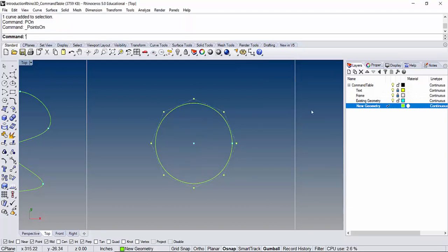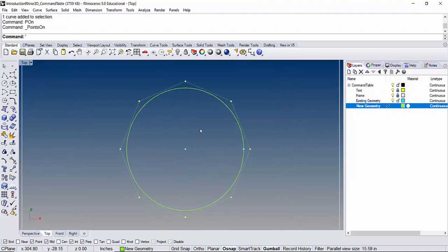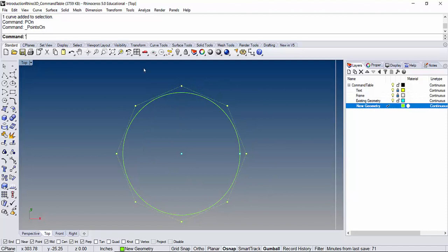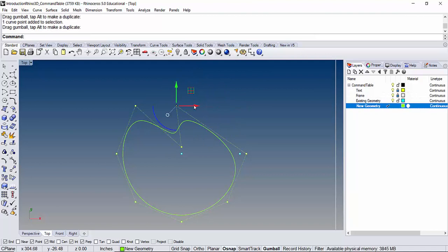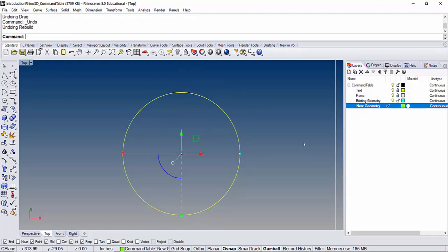Now, if you turn on the control points, you can see that now this is completely different. All the control points are sitting outside. And now if I select any of them, these kinks are not there anymore, right? So it becomes a smooth curve. So 2-degree curves could have kinks, so they could have breaks, but a 3-degree curve is always smoother. So therefore, the default Rhino geometry is a 3-degree curve. I'm actually going to go back, and since this is already in the video, we're just going to keep this as a 2-degree curve.